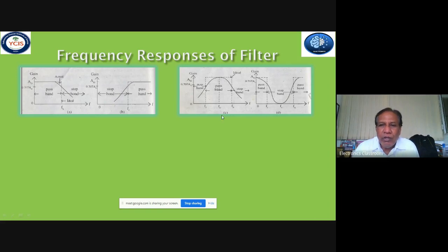drops, okay, and at one particular frequency the gain is maximum, or the current is maximum, or the power is maximum. What I'm saying is that the circuit is more active, or the circuit is more resistive, that the inductive and the capacitive effects cancel each other and the circuit will behave as a resistive one, and that's why there is less opposition. That's why we can observe the maximum current in the circuit, and due to the maximum current there is maximum power, and due to this maximum power we can find the maximum gain, so that at frequency f equal to f0 the gain is maximum.